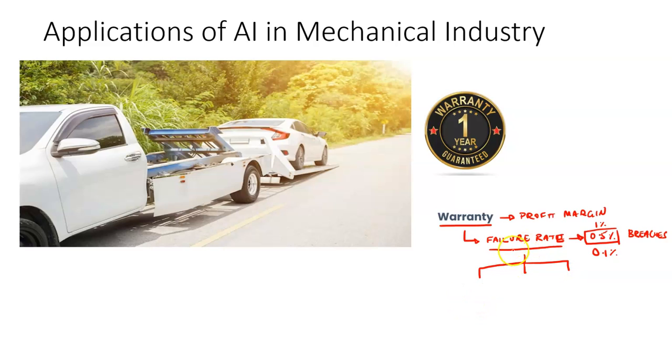So there are three components to what is known as service quality that affects the failure rate. Product quality is important, and what is equally important is service quality. That is how well the service is handled by the dealers and partners. In service quality, the important thing is what is known as no fault found. Let's say a car is down and the partner engineer replaces two parts. In reality, only one part should have been replaced, but two parts were replaced. So this additional second part is actually a case of no fault found. Why should a part be replaced? That adds to the cost. That adds to the failure rate.